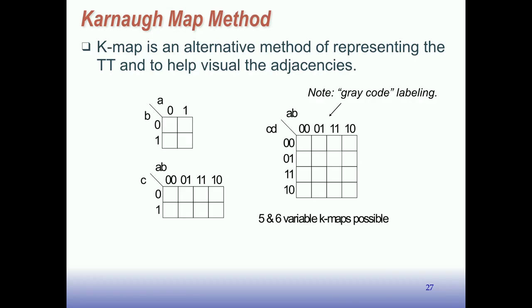So you can see here we go 0, 0, then we change the low bit to a 1, and then we change the high bit to a 1, and then we change the low bit to a 0. Using this principle, we can define gray codes for any number of bits. We can move through all the different permutations, but we only change one column at a time.